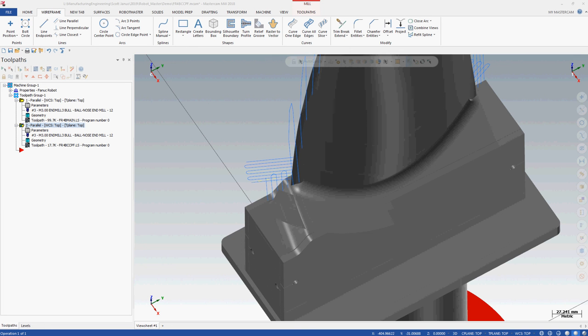And then here's where you change your step over. So I change this to 10. Refresh. You can see now it's wide so that you can make some real quick changes on the fly. You can also break these surfaces up. So if you want one little strip that you want to slow down, speed up, that's easy enough to do. Change that back to 5.